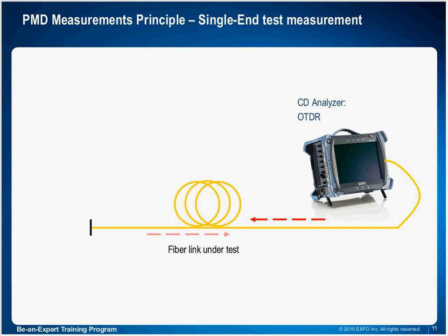The reason that I put OTDR in the presentation is that this type of module is going to be using OTDR technology to measure back reflections at all different positions along the fiber under test, and use combinations of OTDR wavelengths to calculate the dispersion, or the differences in arrival times between these different pairs of wavelengths. I also have this set up ready here to go. We will be looking at both types of equipment and both types of menus, and we'll be getting to that very shortly.